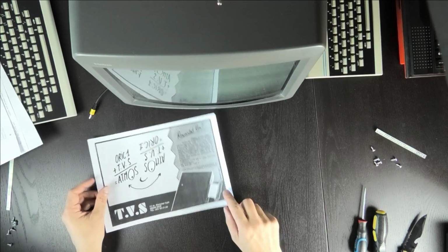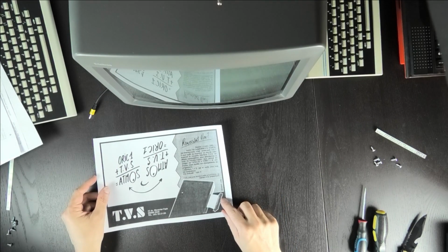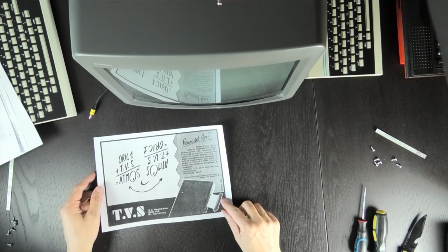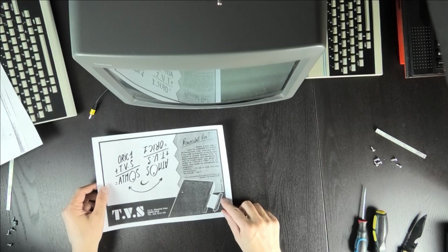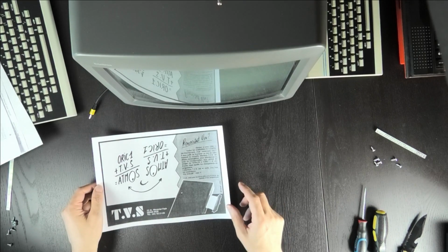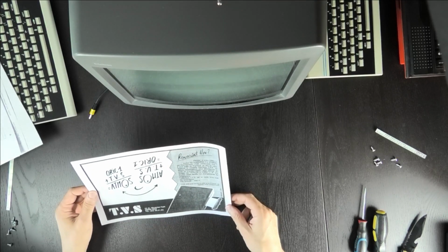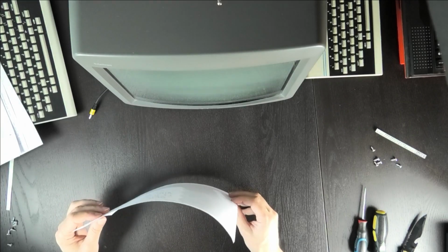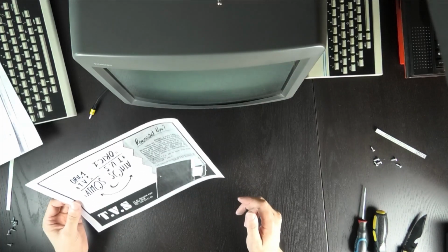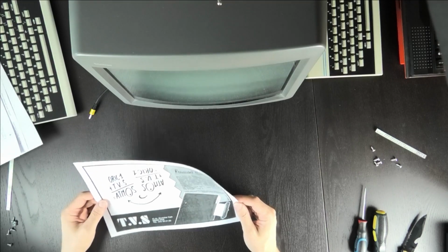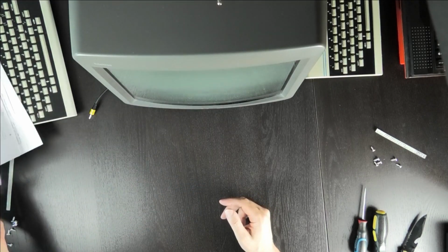So basically what this thing does, it connects to the extension port directly on the 6502 bus, and it probably does the same thing as what the Microdisc is doing, which is short-circuiting the main ROM to use whatever is there. Which brings the question, how the heck did Oric manage to spend up to 5 weeks doing the operation, while all there is to do really is